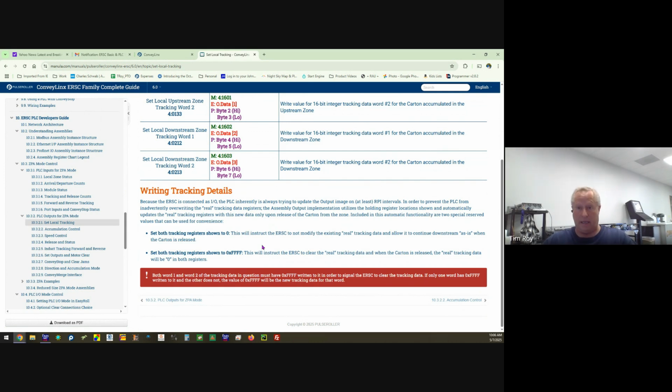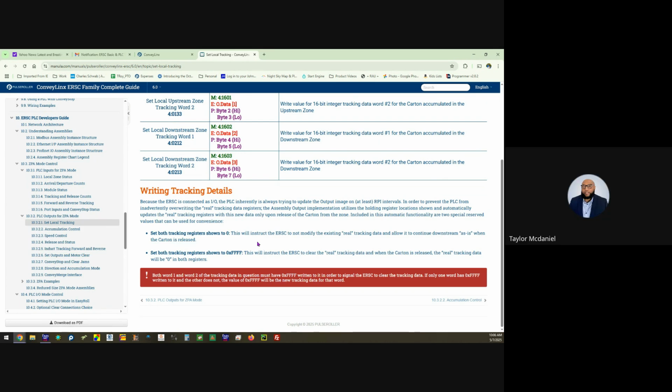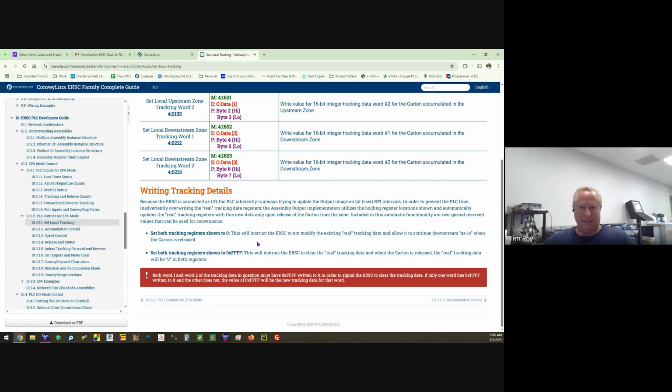How do we overcome that? This gets back to what you were already talking about. We assign it a number, something special to identify it. Then we take that tracking data, and in the low integer we would write the divert lane, 5. But in the high integer, when that first load arrived, we would increment what we call a sequence number. So the first load arrives, the value becomes sequence 1. Put 1 in the high word, a 5 in the low word, release the load. It goes to lane 5 and diverts.